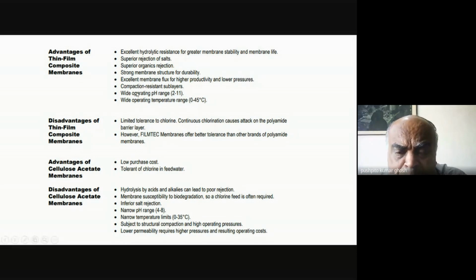Now, this is again very important. When you are applying something like a 70 bar pressure on these membranes, because of this pressure, there can be a compaction which takes place. Now, that compaction can actually close the pores, and your performance can deteriorate very rapidly, right?